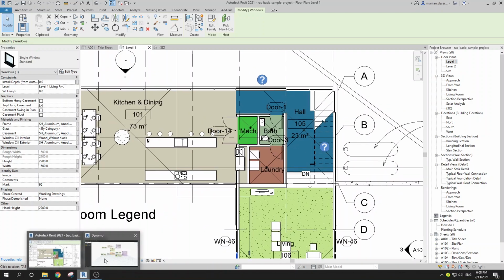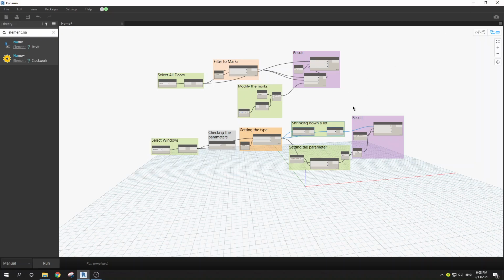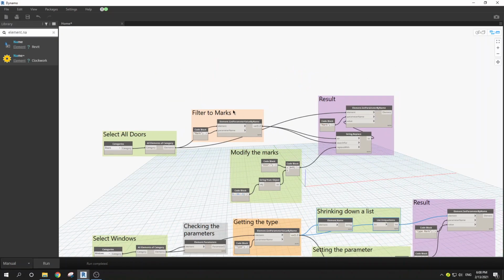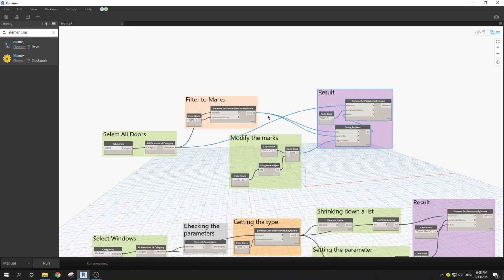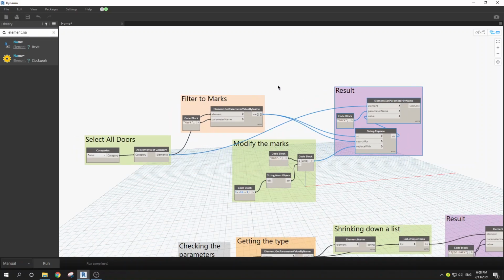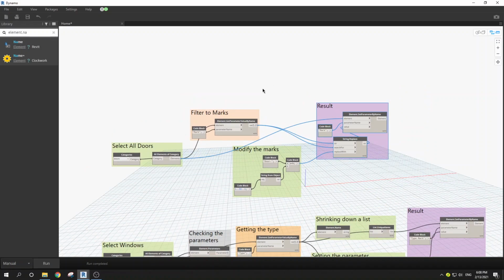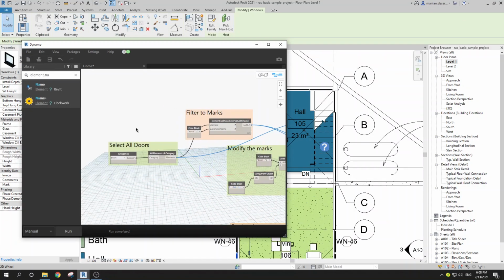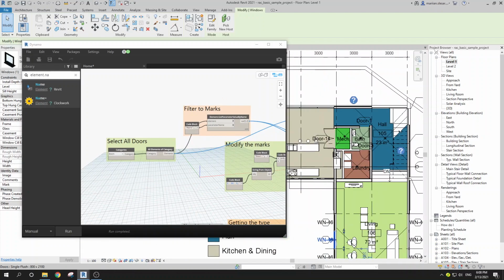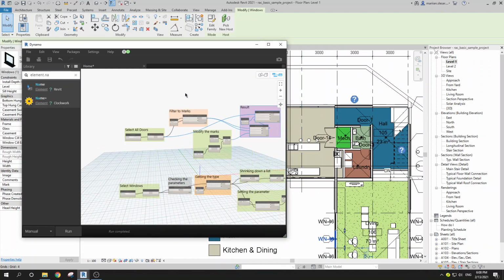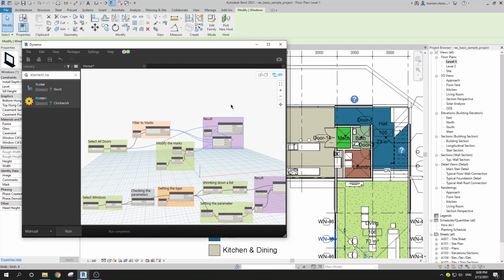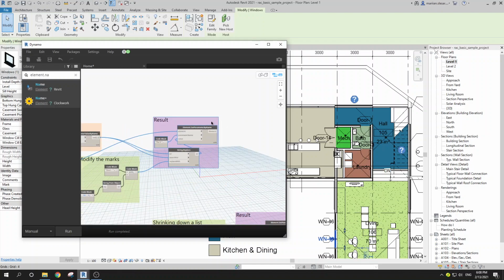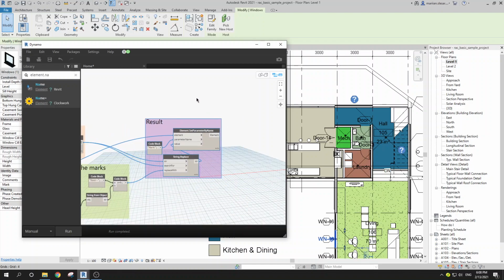And here what I have done, I'm gonna be going through each step. It's not that difficult a script, but it's gonna give you a lot of tips on how to understand Dynamo, just how to get to know this. So first things first is how you need to think in Dynamo at all. What I prefer doing is to work backwards. So I always start to think what kind of a result I want to get.